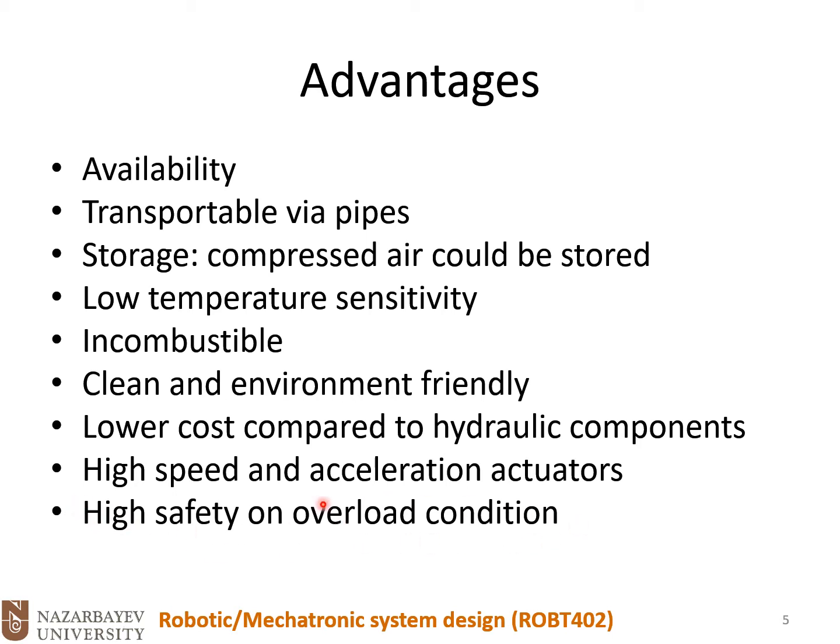So in case the cylinder goes under a heavy load or unexpected load, since the air is compressible inside the cylinder, the cylinder will be compressed, and the damage is limited to the actuator, the cylinder or the pipes, because they could accept some tolerances of pressurized air.